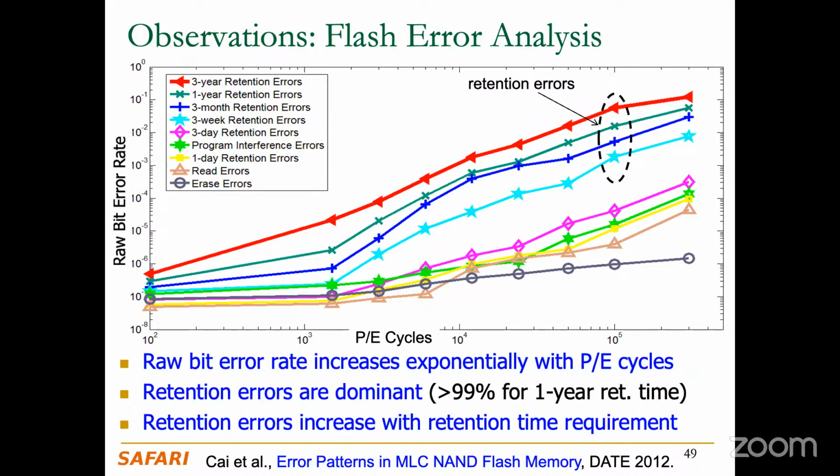And I should also say that the raw bit error rate which can be more or less corrected by ECC is around 10 to the power minus 3. So when your raw error rate is higher than 10 to the power minus 3, then essentially ECC cannot fix it, assuming that you don't have a more intelligent architecture in your system, and your device is going to be dead.